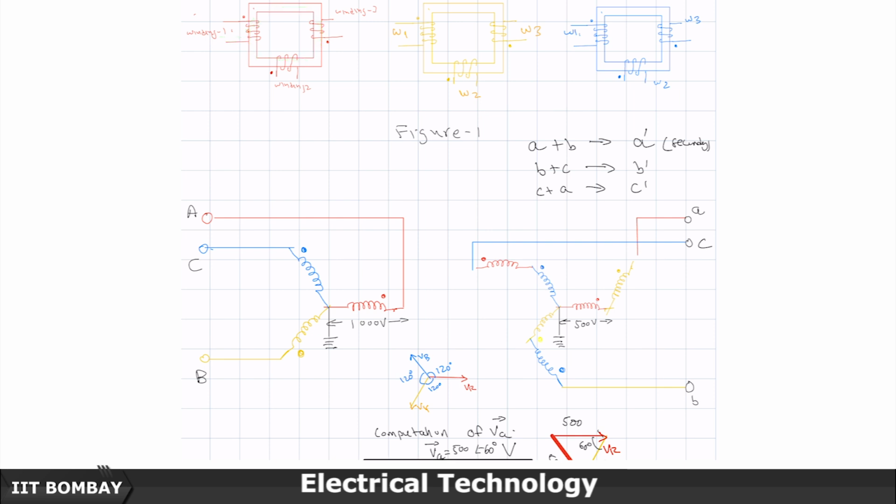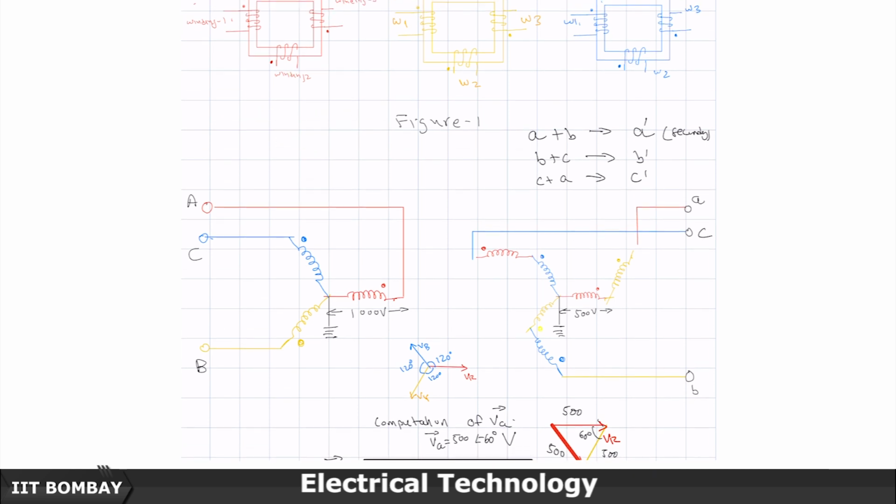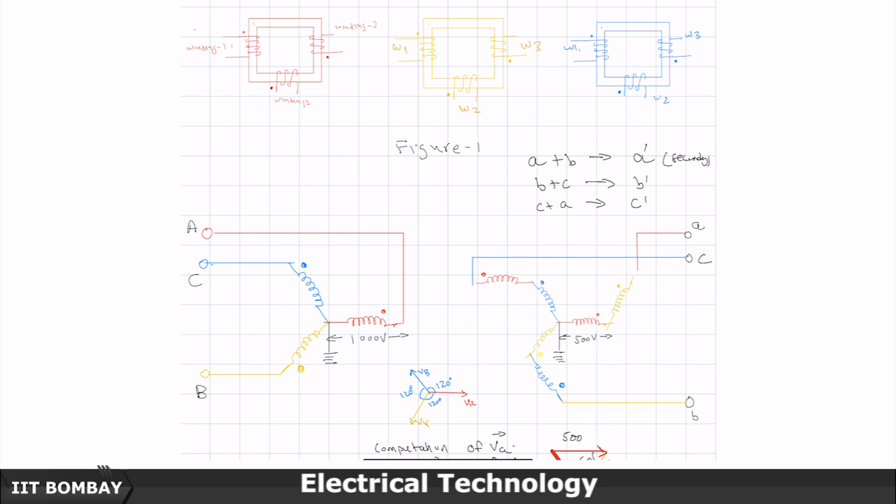So n d phi by dt is the same except for the number of turns. Therefore, if this is V1, then this will be V2 and this will be V3, because they have the same number of turns. So if I apply 1000 volts here at an angle 0, I will get 500 volts at 0 here, and 500 volts at 0 here. Similarly, if I apply 1000 volts at an angle of minus 120 degrees here, I will get 500 at minus 120 degrees here, and also 500 at minus 120 degrees here.